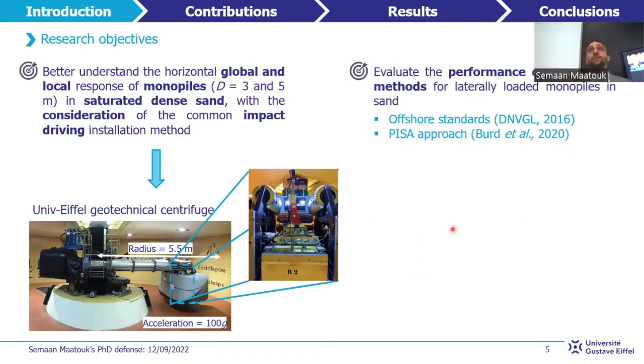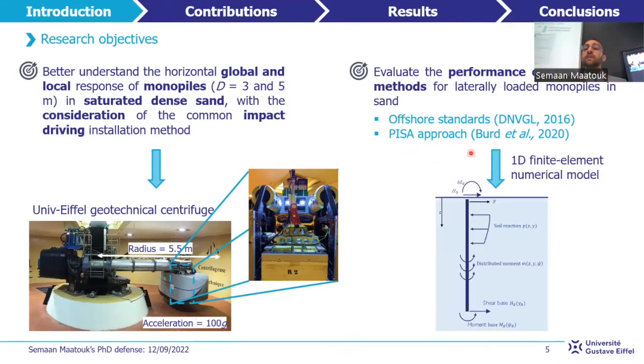The second objective of our thesis is to evaluate the performance of the design methods for laterally loaded monopiles in sand by comparing the experimental results with those obtained by the offshore DNVGL standards and the PISA approach. This is achieved after encoding a one-dimensional finite element numerical model using the Python language.